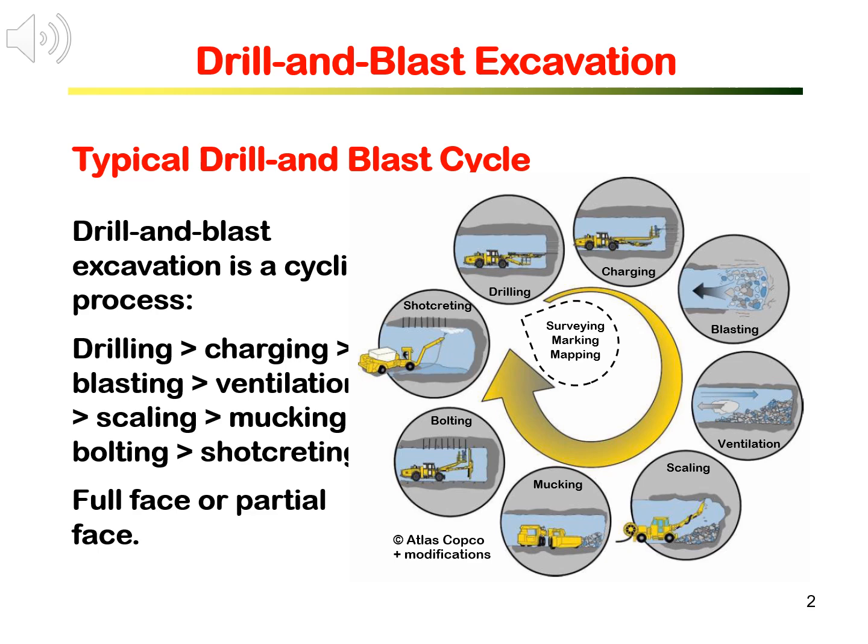The main activities in drill and blast excavation involve drilling the blast holes, charging the explosives into the holes, and setting off the explosive to blast the rock. That is only halfway. We will then need to ventilate the working area to clear the air before scaling down any potential falling rocks, so the mucking and transportation crew can go in to remove the excavated rocks.